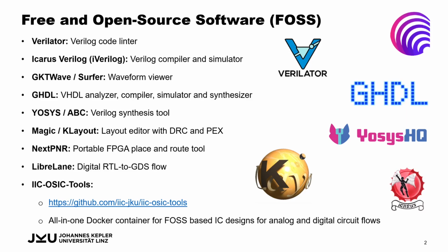Then for VHDL, we have an analyzer and compiler, a simulator and a synthesizer, called GHDL. Then with Yosys and ABC, we have a Verilog synthesis tool. More particularly, with Yosys Slang, we also have a SystemVerilog synthesis tool. Then we have Magic and KLayout, which are layout editors with design rule checks and parasitic extractions, so not only editors, but also viewers, of course. So we can also check our final layout in the end.